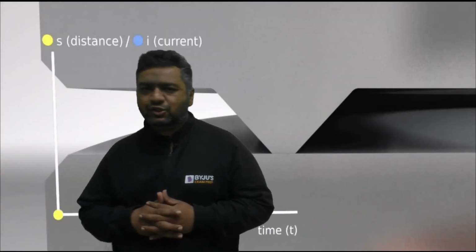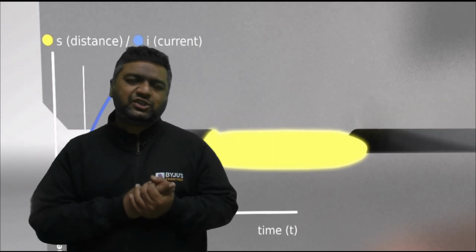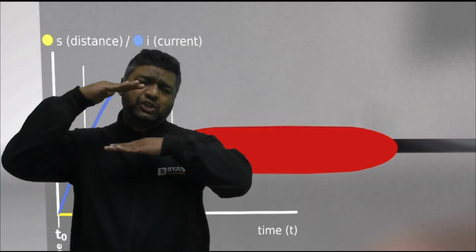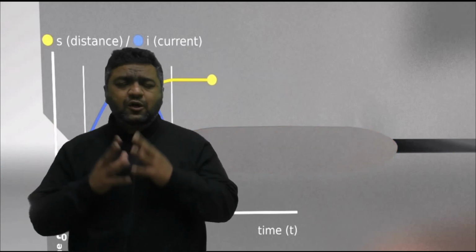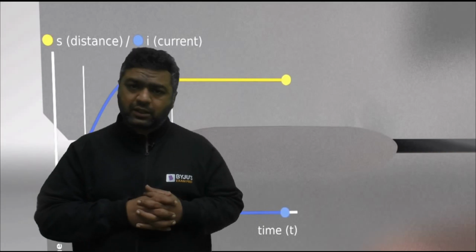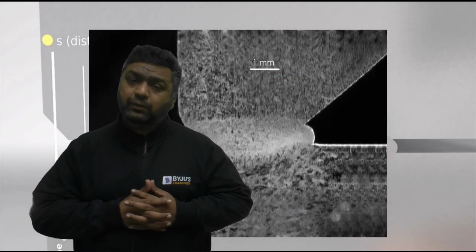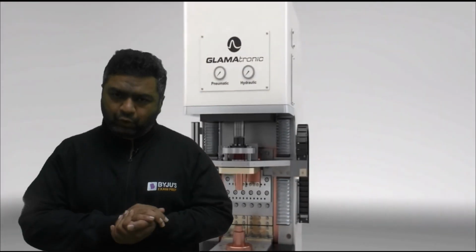We will see them in the metal forming series of Ground Zero. So when we are talking about this, projections are there. Whenever the sheets come in contact with each other, first of all, we apply pressure, because of which the projections will be broken. After the projection breaks, current will be passed, and due to current, more heat generation will happen at the interface and weld will be produced.